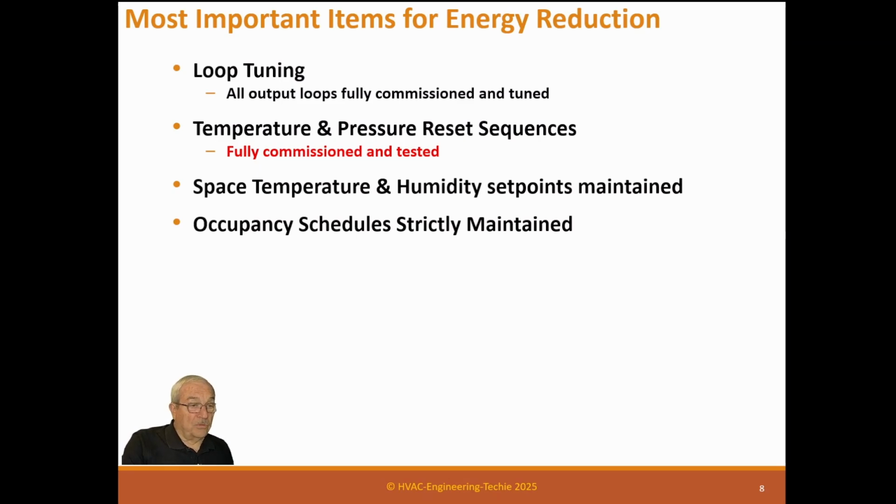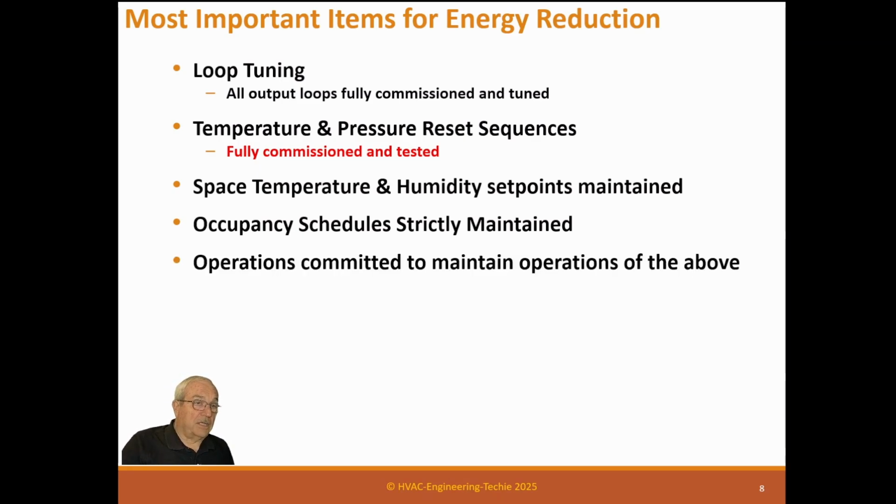Vapor pressure will go right through a wall. So if you have humidity levels different and you have the capability of doing dehumidification, you're going to spend a lot of energy. Occupancy schedule strictly maintained, so we don't change schedules all over the place. Operations committed to maintain these above. So the operators have to be willing to do these to keep the persistence in place and the system operating correctly.